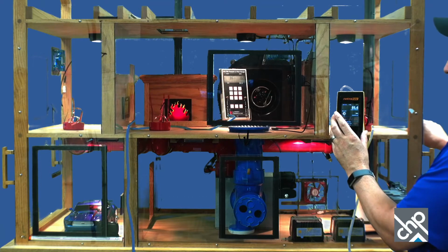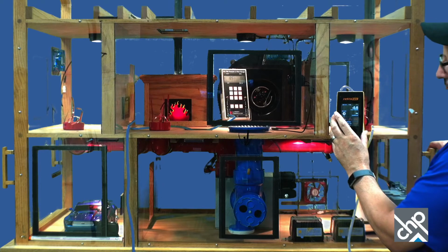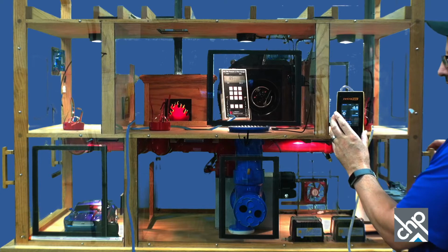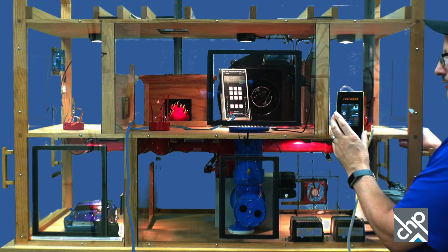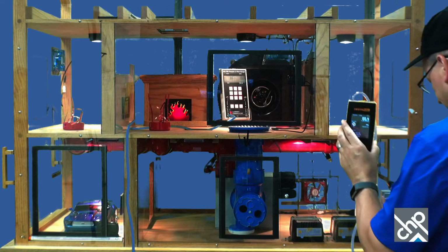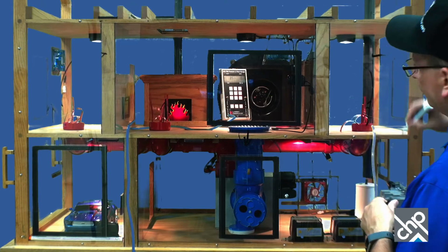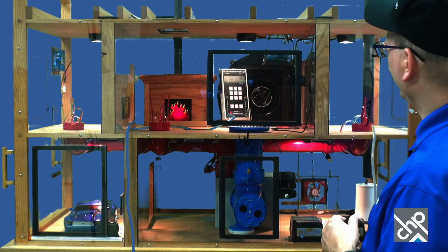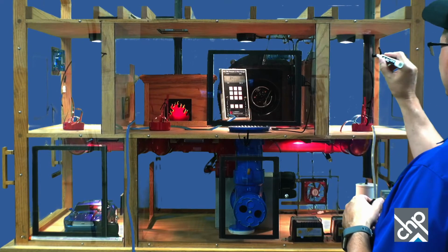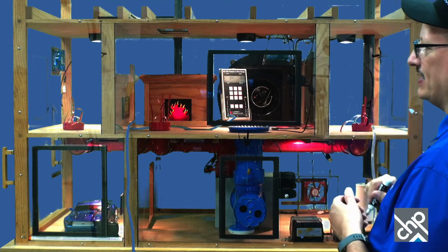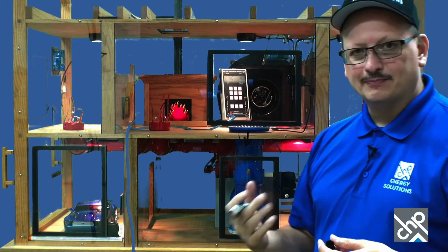So I'm going to open this door. You can watch both of the numbers. So the 50, you see how it dropped down to basically 0, and then same thing in the house. They basically equalize the pressure. Of course, now my smoke's starting to go back up the chimney too when I open the door. And if I close it back, it gets trapped behind the door. You see the smoke coming right back down the chimney. If I indicated this with a plus sign here, then that's, I got a little green screen, so the plus don't always show up. But anyway, you guys get the idea that it's positive there.